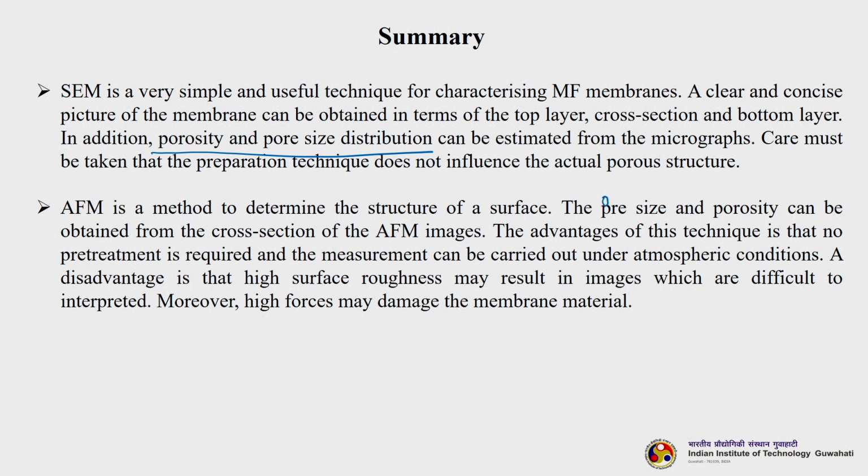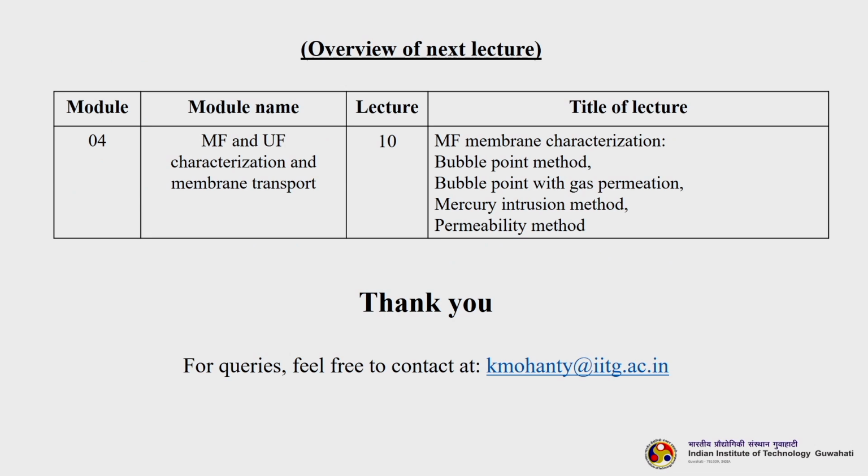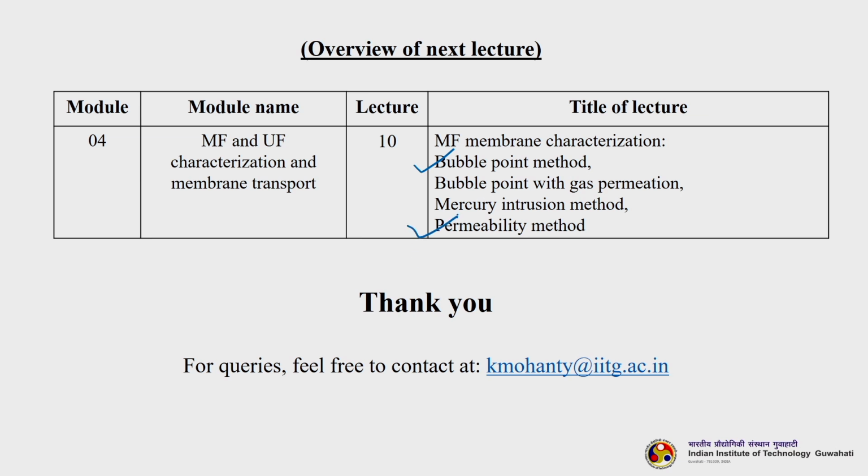Students, today we understood three important membrane characterization techniques: SEM, TEM and AFM. For the next class you can refer to these books. In the next class we will understand some other techniques, which are called the bubble point method, bubble point with gas permeation method, mercury intrusion method and permeability method. Some of these methods, like the bubble point method as well as the permeability method, can be done in anybody's lab with very small setups, and you get accurate results also.